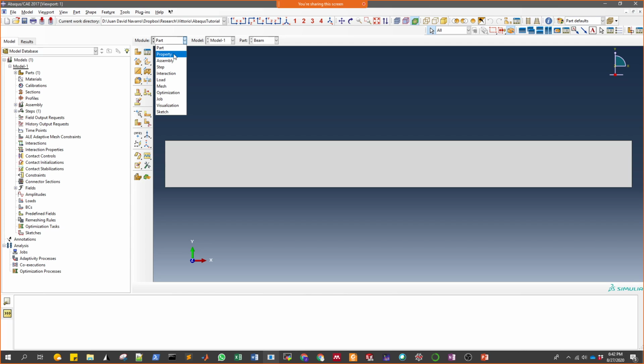So let's continue to property. Okay, here you have more controls. You can do extrusions if you are modeling 3D bodies. You can also extrude shells. You can do extrude cuts through material. So if I want to have a hole here, I can just draw a circle there and then extrude that circle.